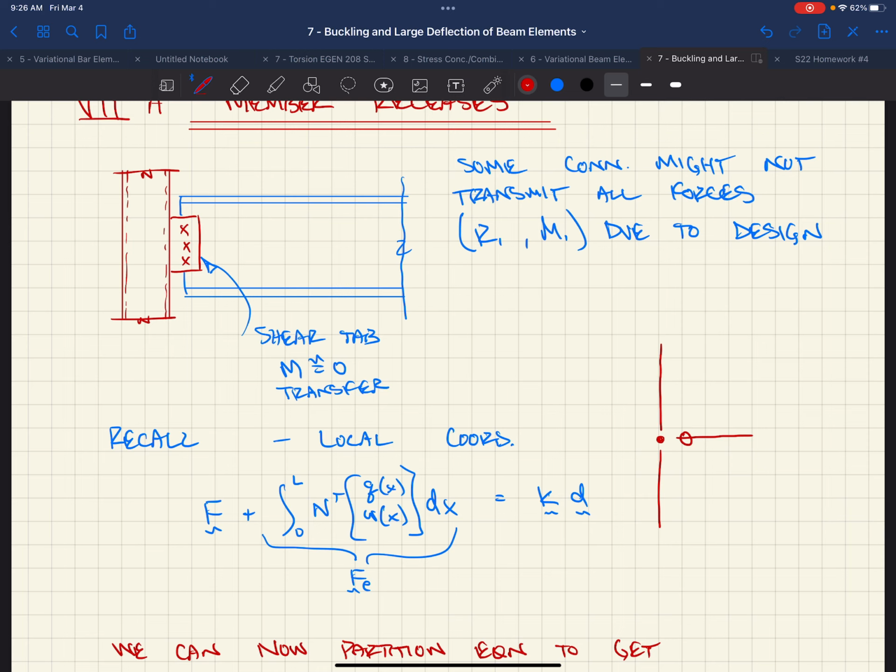So one thing, like on the dining hall, for instance, those are all pipe columns, and we have shear tabs going into them, right? In some cases, you'll see in that building, the shear tab, we ran completely through the column because we had certain conditions where the loading, so you have to start thinking about, as the beam sees it, there's zero moment transferred, as the tab sees it, zero moment transferred. But when you start looking at the eccentricity, you really have this beam that's landing on these 3 bolts. Well, now if you looked at a tube column, you have this knife edge that's trying to rotate. And so I would go through and look at, okay, what's going on, chapter K in the steel manual.